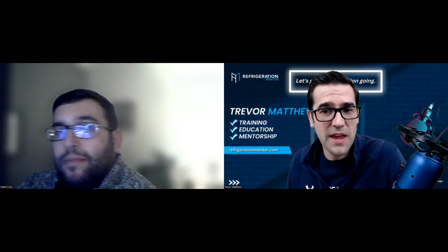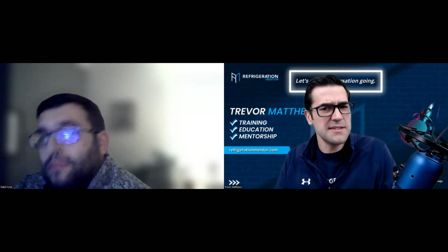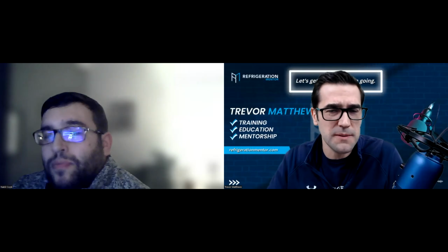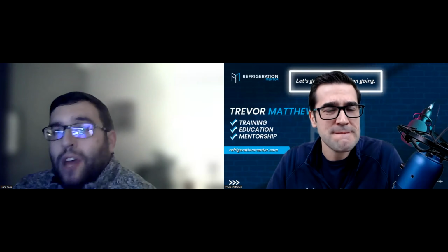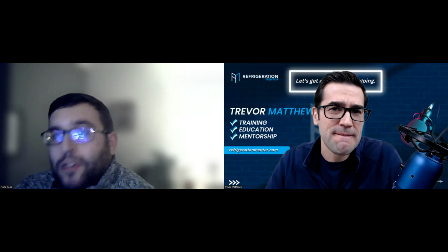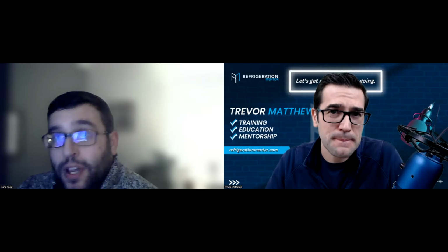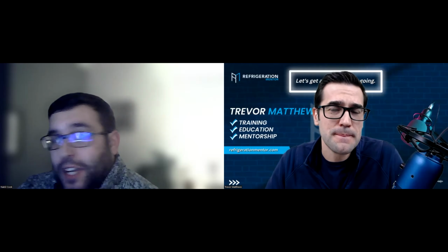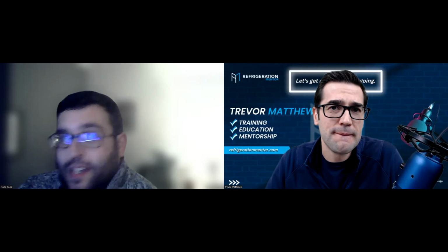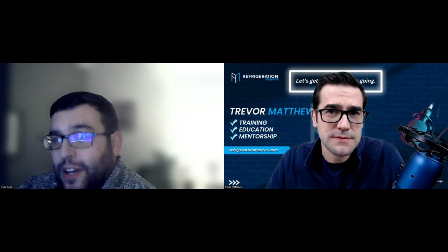Yeah, because that's the main things you need when you're going to design a booster rack, right? That's some of the main things, right? Well, that's it. Compressor sizing is all based on compression ratio and displacement. So the most fundamental thing you need is an understanding of those SSTs and also that high side condition.